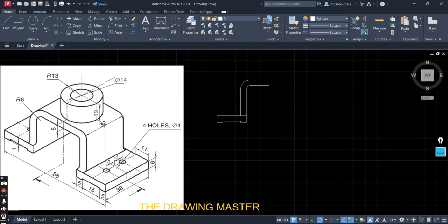While preparing the manual drawing, here you have to mark the center, and from that center you have to take the radius 3 and 8. Right? Instead of using a compass, you can use the circle master also. That is easily available in the stationery shop to draw small radiuses. Now we will use the mirror command here. Before the mirror command, we can draw the hidden hole here.